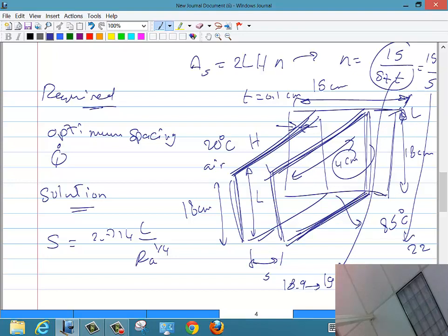So mathematically, what you did was right. You'd say 18. But practically, you will say, no, I'm not going to go for the optimum Nusselt number because I'm going for actually a bigger area. To optimize my design, the heat transfer rate is bigger if you use 19. So by adding another fin, you actually make it more optimal because you get more transfer because you have more area. You will make the Q higher, but each one of those fins is not optimized.